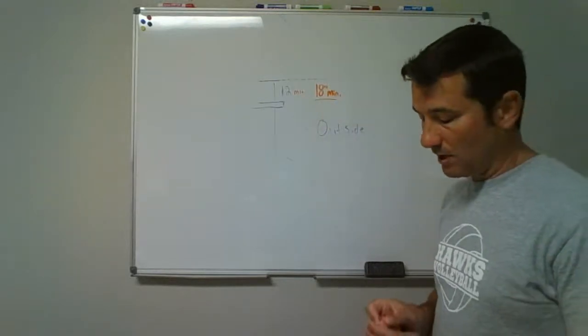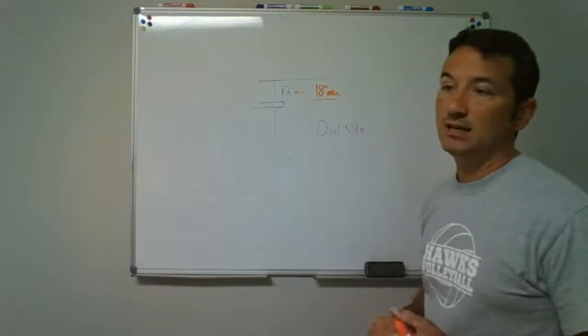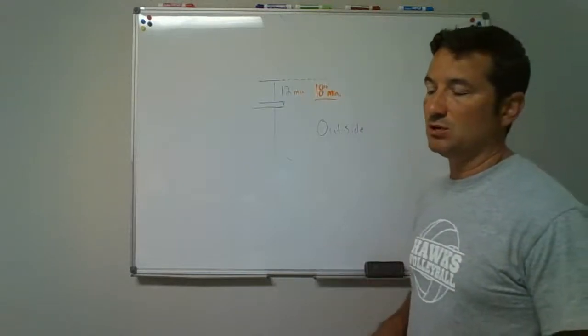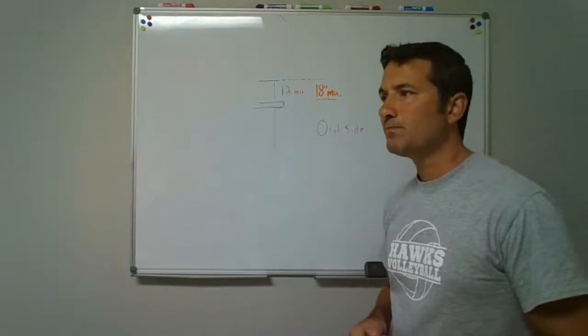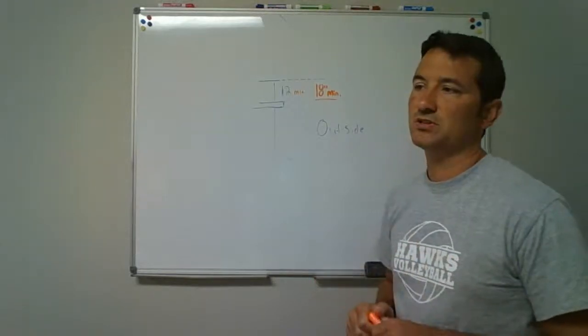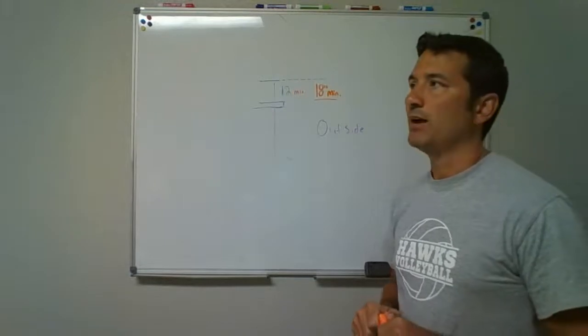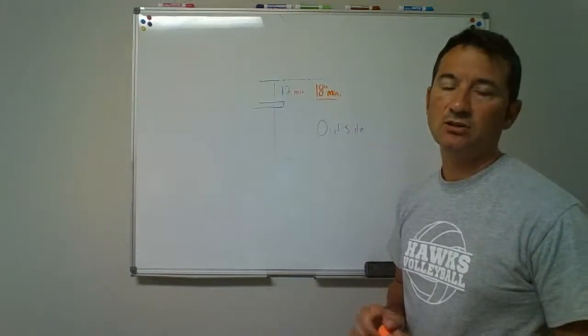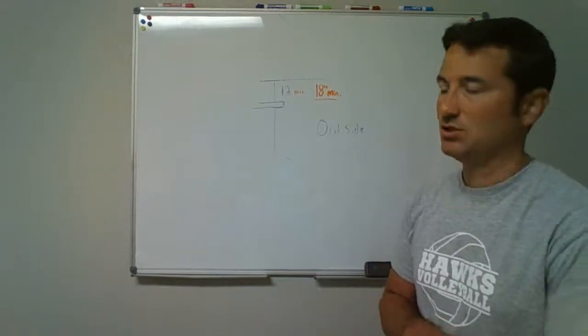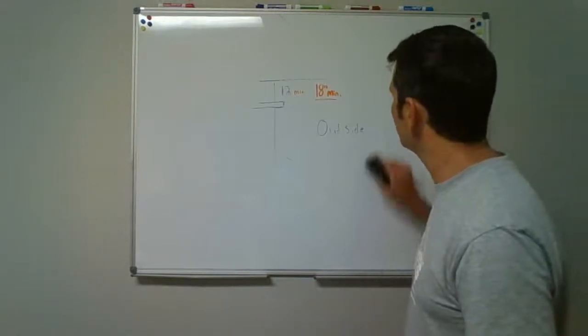If you read something where the manufacturer said the maximum distance was 8 inches, and the code said a maximum of 10 inches, then you're going to go with the maximum of 8 inches. Follow what's most restrictive.